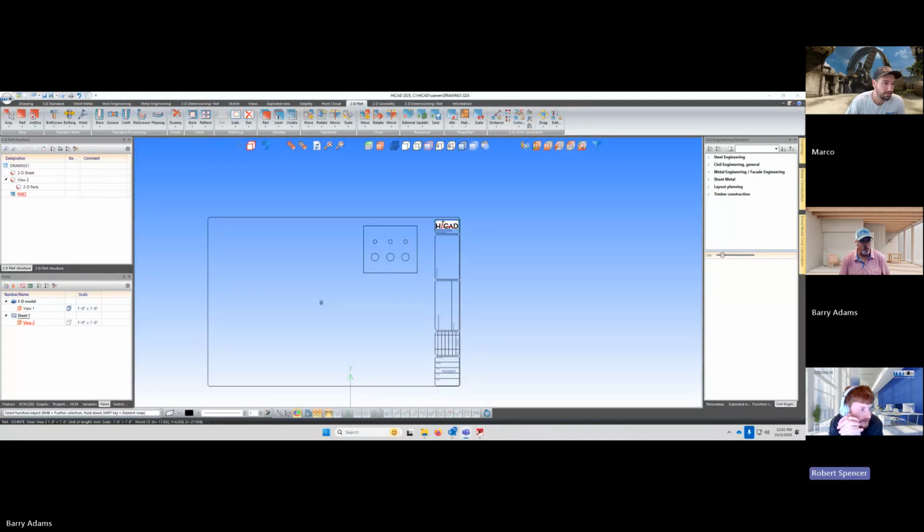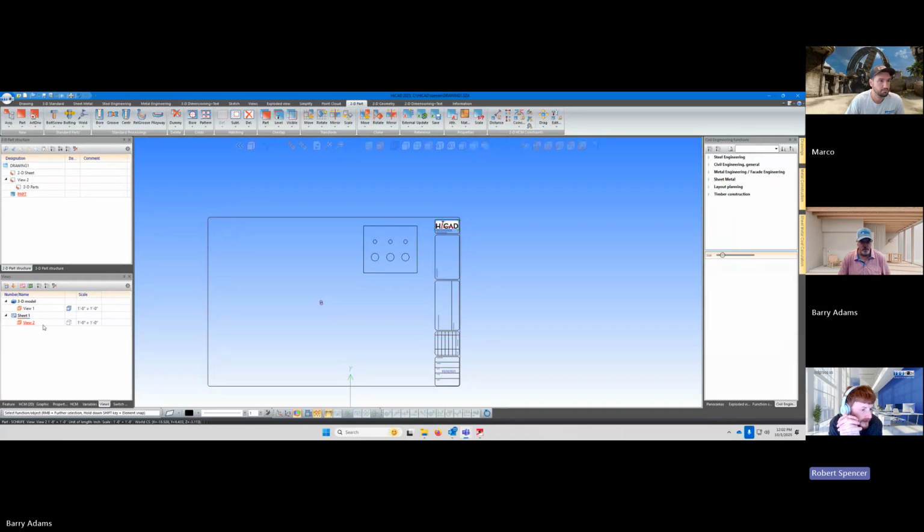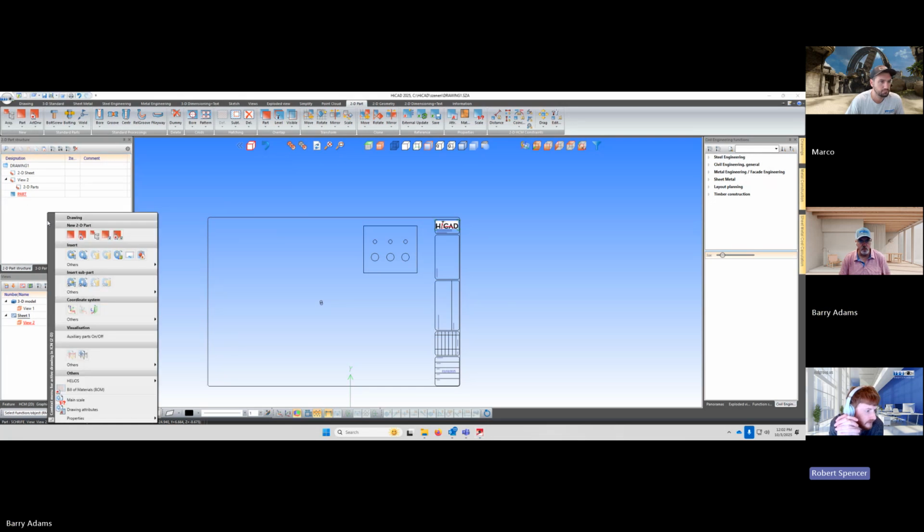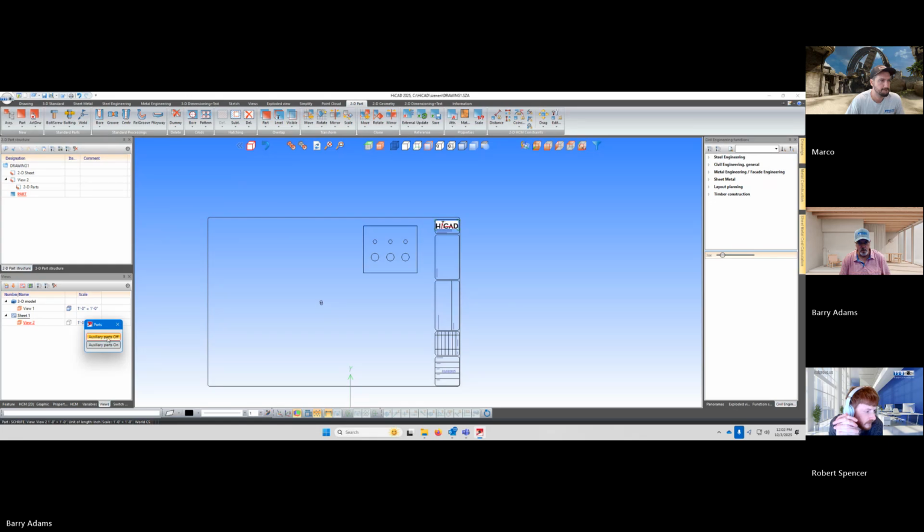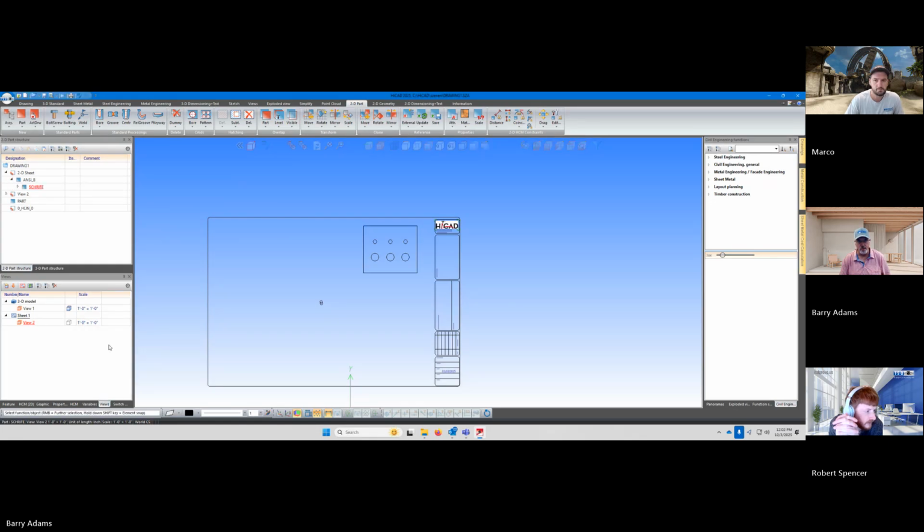Oh, okay. So were you able to switch on your auxiliary parts? In fact, I don't think you have to switch it on, but I want you to know that. And I see it doesn't look like you do. So up in your 2D structure, can you find the 2D part structure? There it is. This one? If you right click in the empty space, I think it has to be kind of down below there. And you see that visualization auxiliary parts? Yeah. So toggle that and then say on. And now your title block appears as a block here in the structure. You see that?